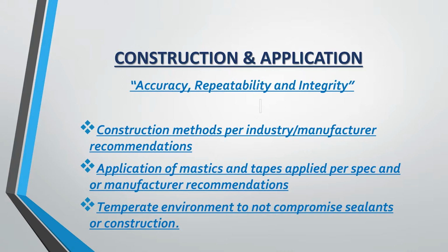Accuracy, repeatability, and integrity for construction and application. We talked about this a couple minutes ago, or I did. Temper and environment not to compromise sealants, application of mastics, construction methods per industry manufacturer recommendations. So when you're doing mastics or any kind of tape, they have a recommendation for how you should put it on, when you should put it on. Time of year, temperatures, all that neat stuff. They should be followed. They're there for a reason. They know the failures. They know the successes of their material.